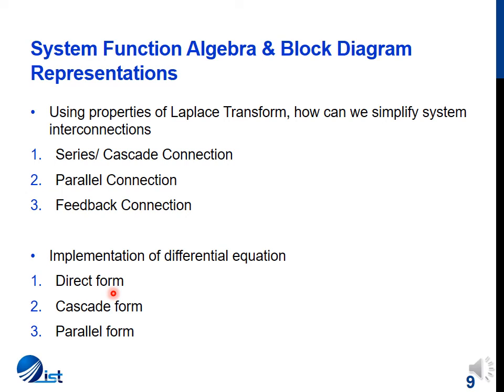In the first way, which was direct form 1, we saw how we can implement the system in cascade in such a way that the pole part is implemented later and the zeros part is implemented earlier. So it is a cascade connection of the zero system and the pole system.